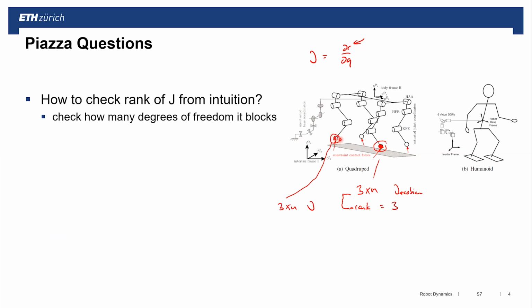As we can see, this constraint here must have these 3 joint angles in the parameterization of that position. That is the Jacobian part of the joint dependent aspects. So in other words, this one must be depending on these 3 joints, while this one must depend on these 3 joints, so they can't be linearly dependent. So if I'm looking at the total rank of this Jacobian and this Jacobian, the rank must be 6. So I'm looking at 6 constraints that I'm imposing if I'm just looking at the rank of J.